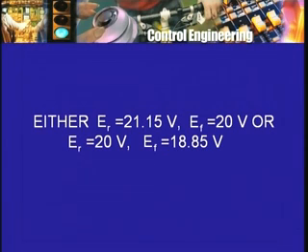But the two are not equal. 21.15 is not equal to 20. Of course, you can say that 20 is some fraction of 21.15 volt. Surely it is. But that way any number is a multiple or a fraction of some other number. There is no great significance. In the first arrangement, there was no potentiometer being used. The reference voltage was 21.15. The tacho generator voltage was directly connected into this difference device. There was no potentiometer used, there was no multiplying coefficient used at all.